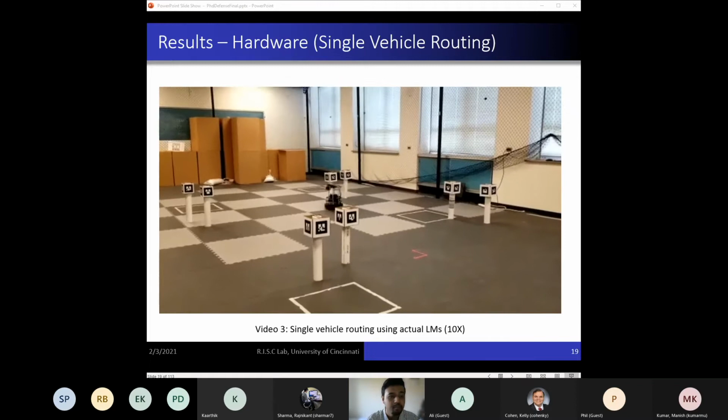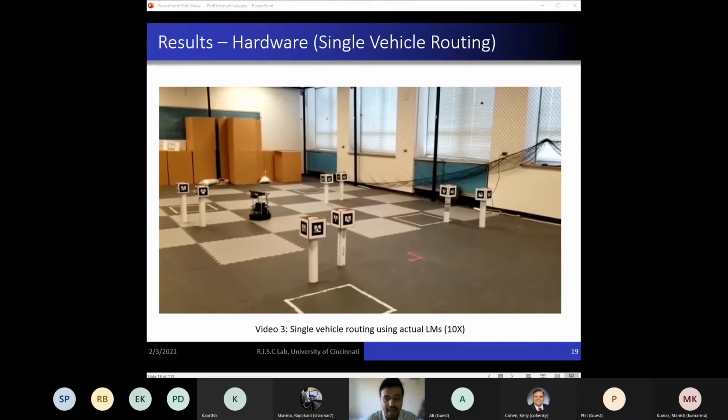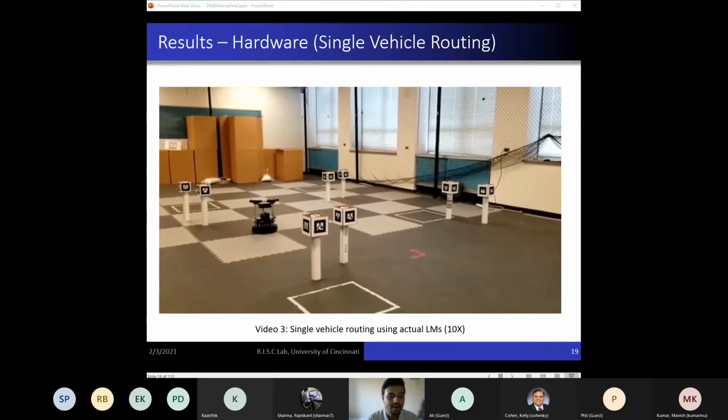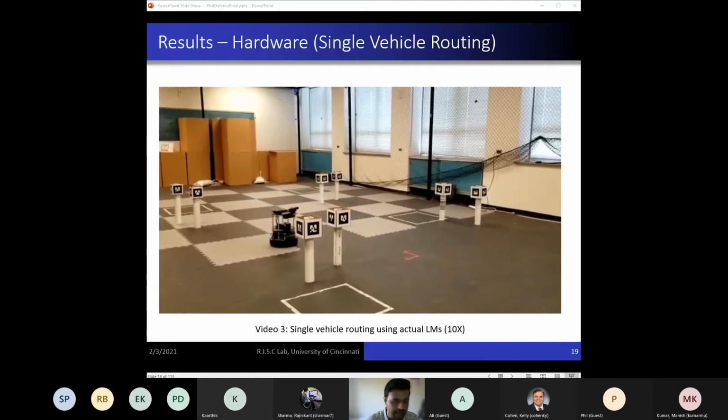We also performed a closed trajectory run with AR tags providing range-only measurements. So at any given point in time or trajectory, the vehicle has a path to 2 landmarks. Using these optimally placed landmarks, the vehicle was able to route through the given set and sequence of waypoints. This is shown in figures 16 and 17. The route is obtained using estimated states. It can be seen in figure 17 that the system remains observable and the bounds are tight and decreasing with time, even for this system. These were the related papers.